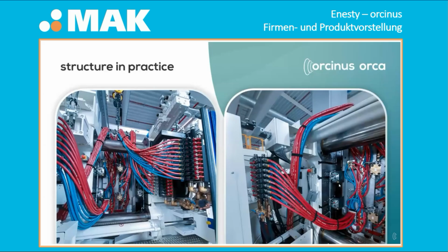And here you have an additional supplement, multi-coupling, which makes the process really reproducible, because every time you have a mold change, the distance from the manifold to the mold is the same because you always use the same length of hoses. You always have the same diameter of hoses.